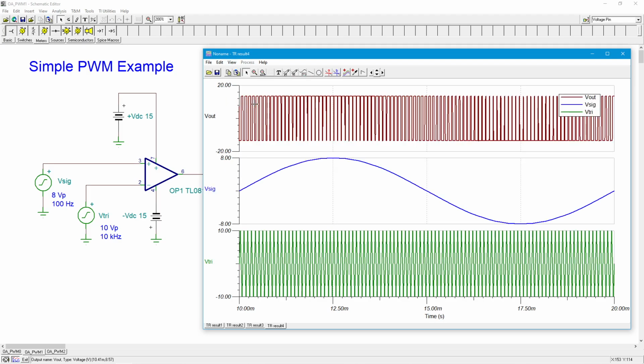So if you were to send this pulse train off to, let's say, a little transistor that was switching an LED in line, or a little bipolar transistor kind of thing, what would end up happening is when these pulses are nice and fat, you're getting a lot of current through the LED, and the LED is going to be bright. And then when it gets skinny pulses, you're not getting a lot of current, when you average it out.